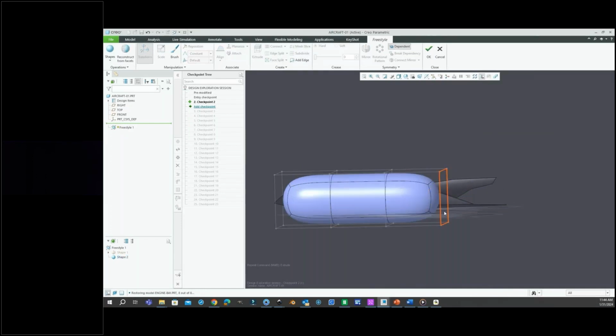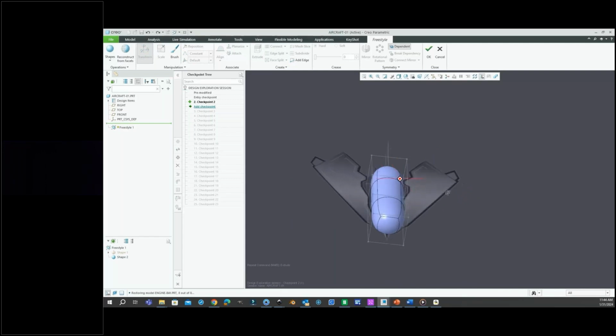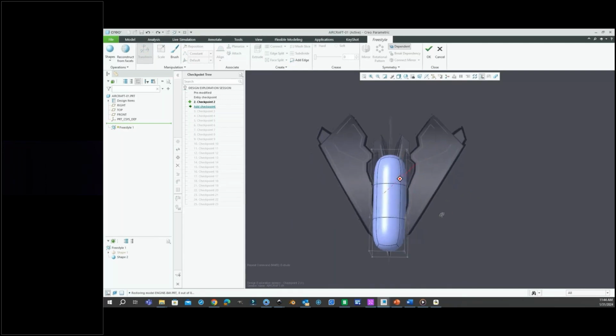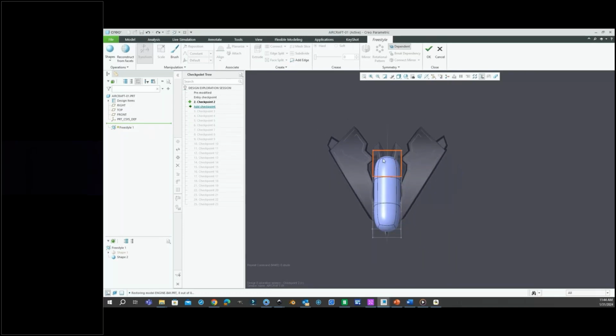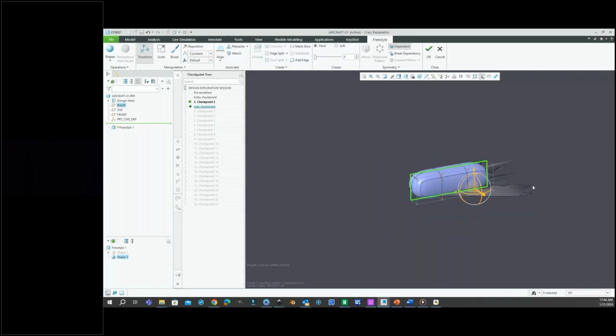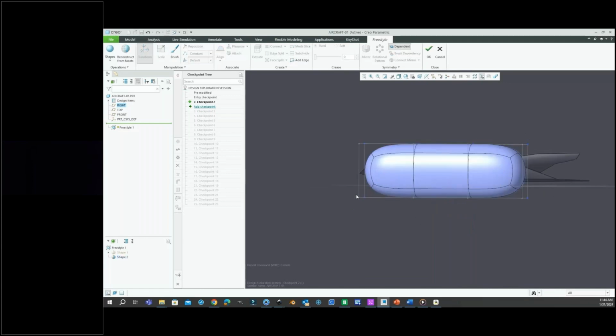And I can start to tweak it a little bit so I can try to get the curvature of that plane by tweaking the vertices and the edges and moving them. What's nice too is we also have the mirror tool. So we know that we'll save a ton of time using that mirror tool, because we only have to modify or design on one side. So to do that, I would grab one side of that mesh, use the mirror feature, mirror about the correct plane, and then from here, I can start coming in and sculpting.